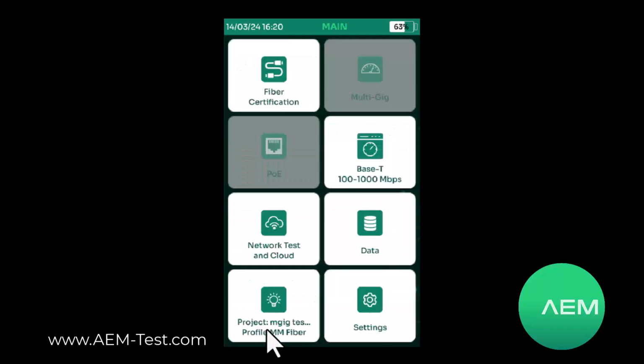You may have noticed when I saved these results, we just allowed it to save automatically from our default list. And you can do a save as. There was another button there called save as, and you're used to doing this if you've been using Test Pro for a while. So I could have clicked the save as button when I did my test reference cord and just called it a TRC instead of using one of the labels in the label scheme. That way I immediately identify it as my test reference cord.